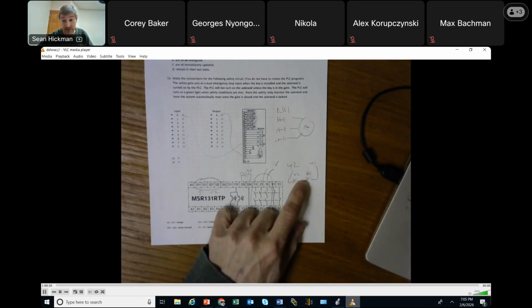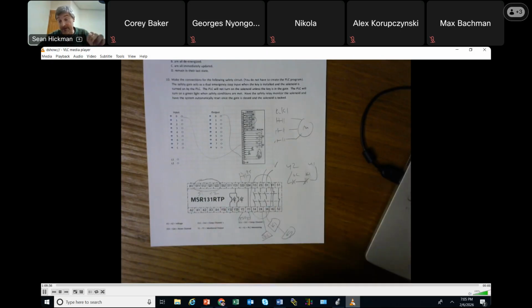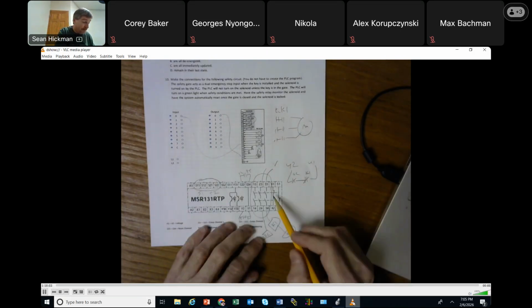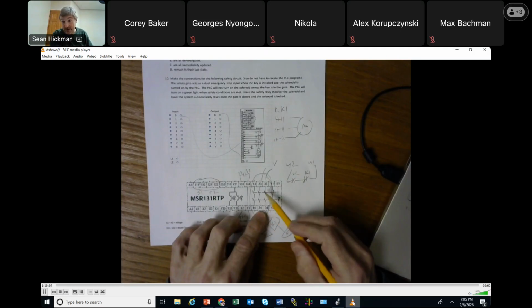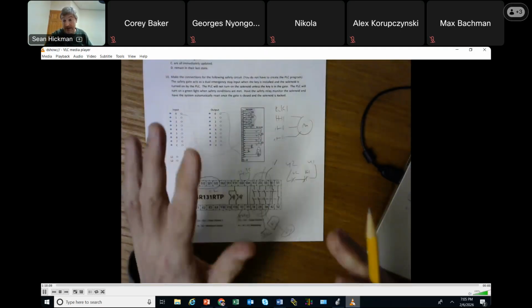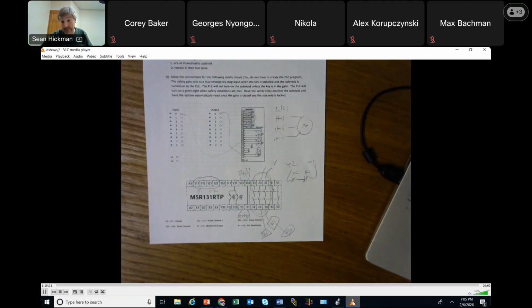But what do you want in series there to be sure that everything is in the state that you want it to be in, okay? And so once again, the final thing is, everybody, scale of 1 to 10, everybody understands that these are the contacts. These are the good ones that are shutting down the field device directly, killing voltage to the field device.